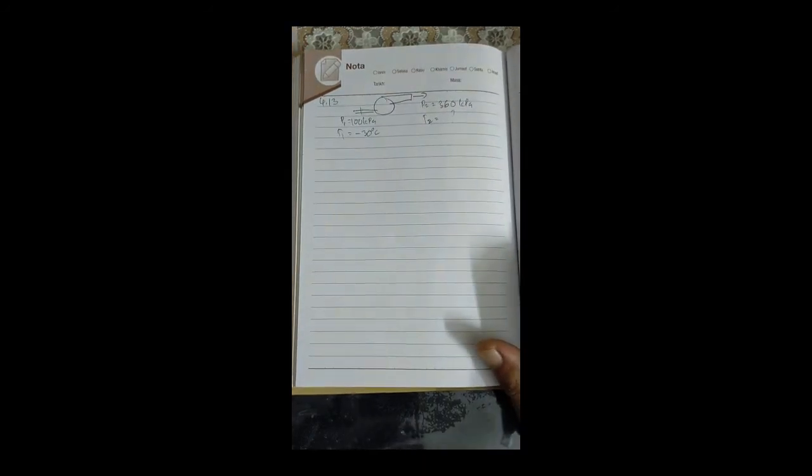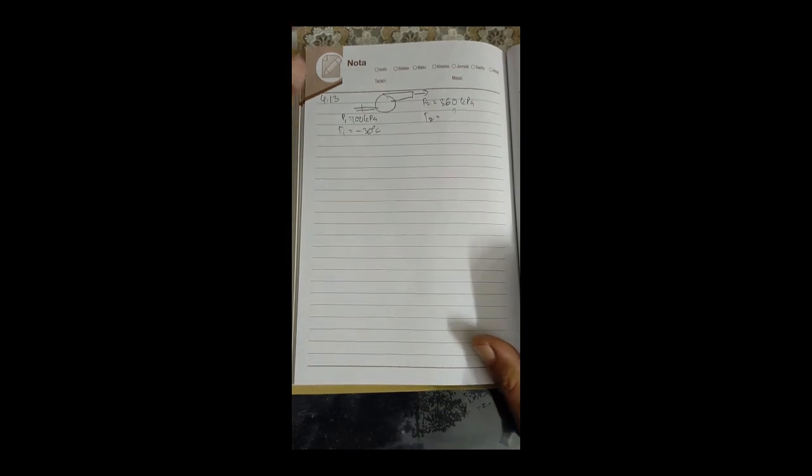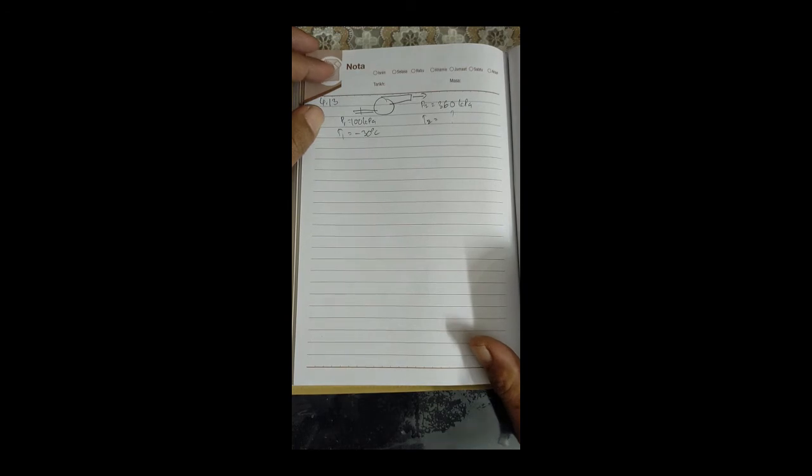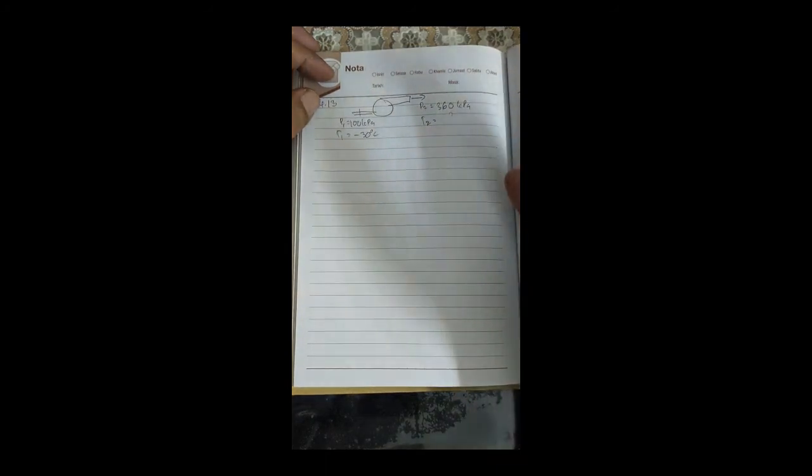Bear in mind, a pump is normally used for compressed liquid. Basically, a pump cannot operate in a mixture condition because it cannot deal with a mixture. If there is air or some mixture in the liquid, we call it an airlock. So normally a pump operates with 100% liquid. That is the normal condition.